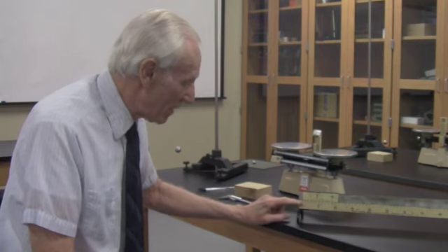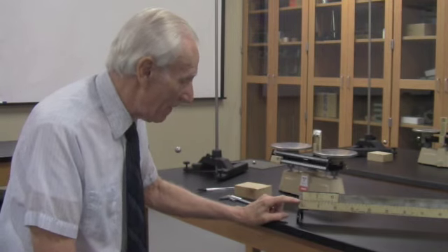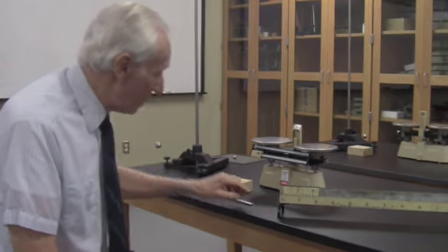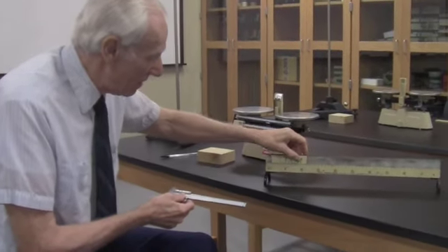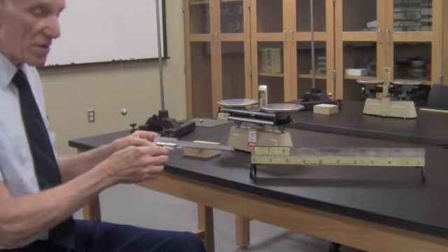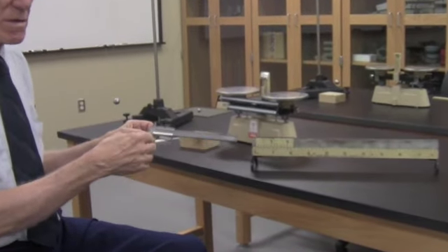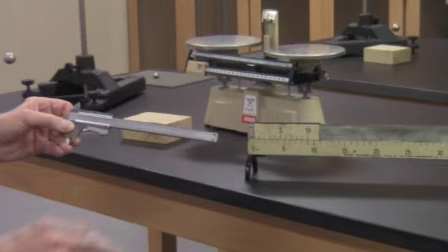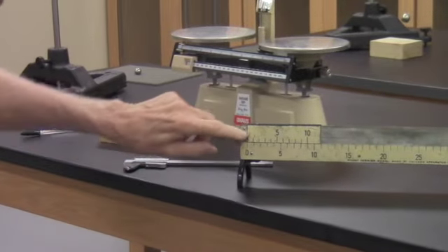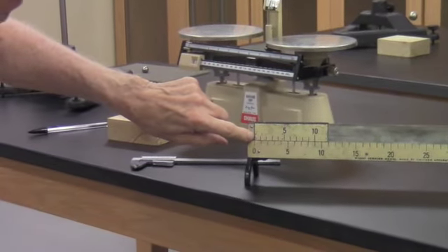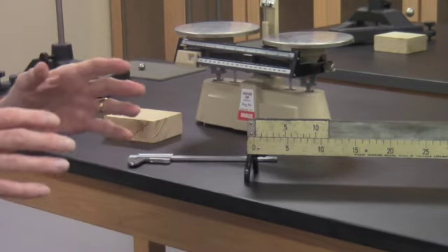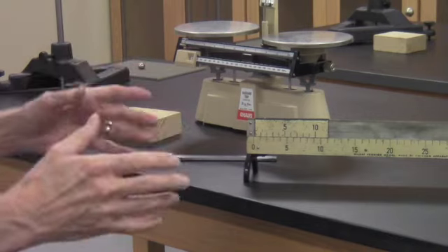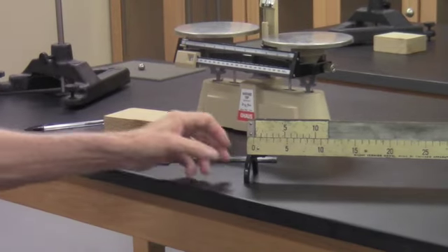Now, the index mark is this mark right here, and the mark right above it. The sliding scale is on top here, but the sliding scale and your caliper is underneath, so this is kind of upside down. So this is actually your index mark on the sliding scale. Wherever that mark is, that is the reading, that is the length that you're going to measure with the caliper.